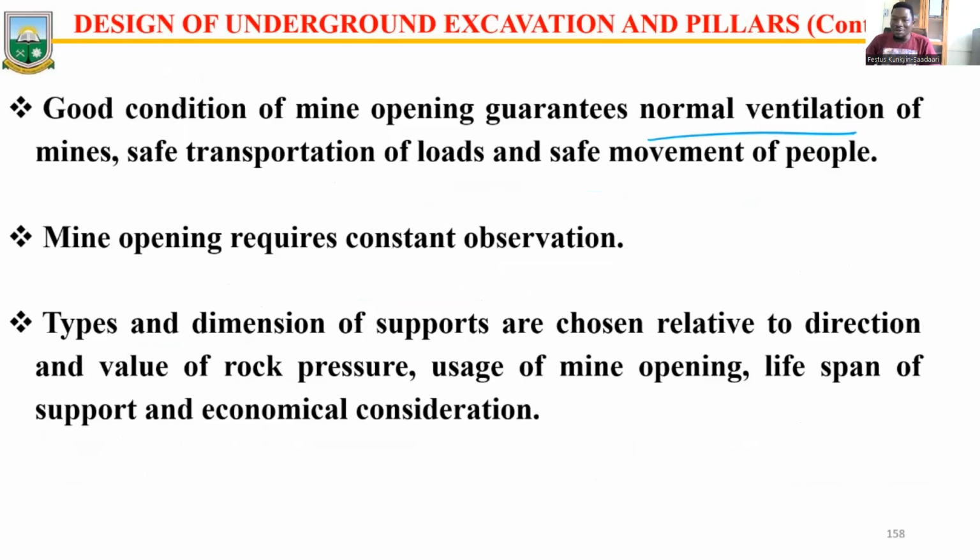Okay, but assuming these things are not done well, you try to pump a certain quantity of air, and this air finds its way through certain cracks, and then they escape. And the man who is working at the face, who needs that air, is not getting that quantity. Meanwhile, you have also calculated very well, and you've distributed your air thinking that, oh, there are 10 people at the face, and so giving them this quantity of air is enough, plus their machinery. But then there are cracks all over, absorbing the amount of air you are sending in there.